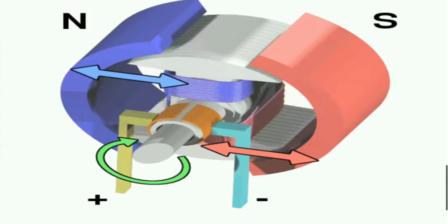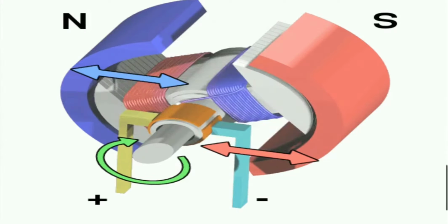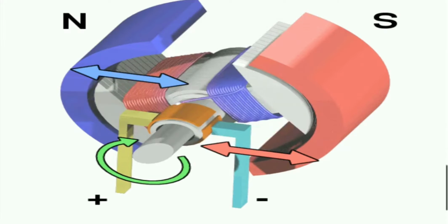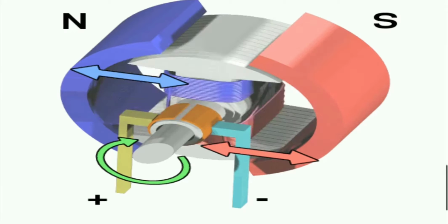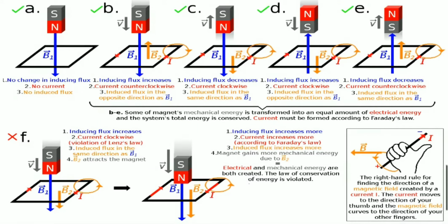The induced currents in the rotor windings in turn create magnetic fields in the rotor that react against the stator field. The direction of the magnetic field created will be such as to oppose the change in current through the rotor windings, in agreement with Lenz's law. The cause of induced current in the rotor windings is the rotating stator magnetic field, so to oppose the change in rotor winding currents the rotor will start to rotate in the direction of the rotating stator magnetic field.